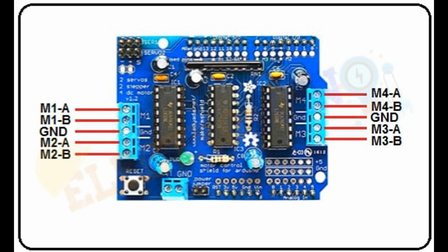Advantages: BLDC motors are more efficient than traditional brushed motors and require less maintenance due to the absence of brushes. They are also quieter and can provide higher torque and speed at smaller sizes. Applications: used in robotics, drones, and electric vehicles, as well as in applications requiring high efficiency and precision. Examples: VESC, open source controller for BLDC motors, ODrive, and Trinamic.